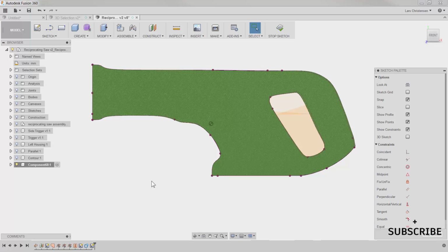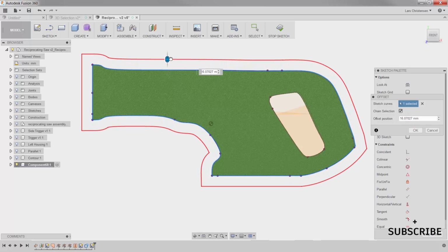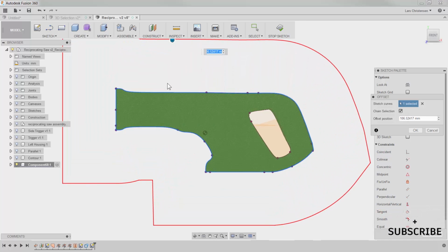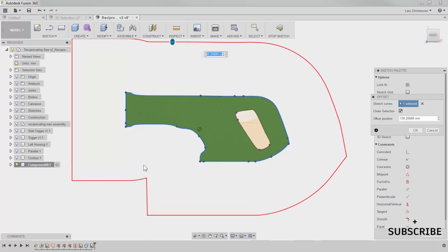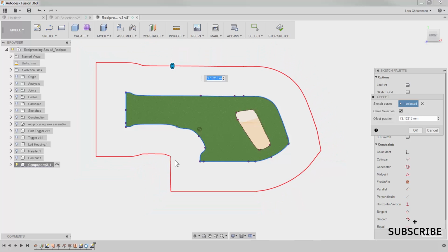But what I'm actually going to do is use the offset command. I'm going to just hit the S key here and hit offset, so I get the offset command right here. And I'm going to grab this edge and just start dragging it out. Now notice this area right here. See how that is kind of curved in? Well, because I am offsetting it out, I can actually eliminate that whole edge pretty much if I just go far enough out. Right? So now it's a line and it doesn't have that development, because that development is what's going to lead the collapse.